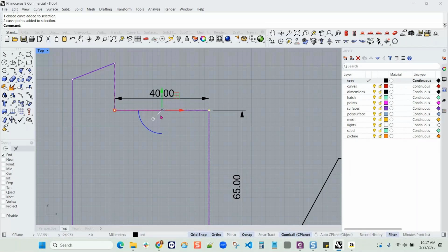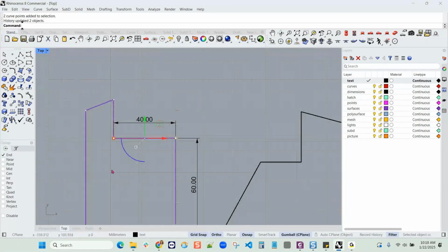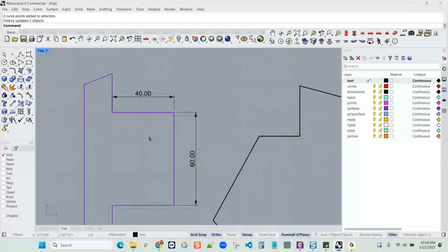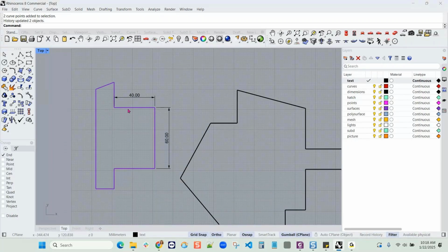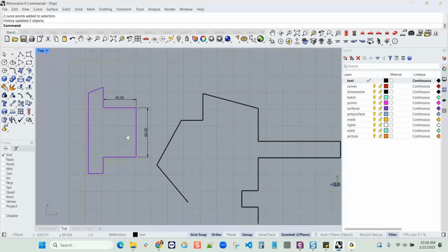So I'll just know they're there. I can make them bigger in the display mode. Let's say here, I want this to be 60, so I'll type in -5. And I do that all day long with architectural floor plans. Okay, so I not only see the dimension, but I'm able to correct it, and the dimension updates with that new distance.